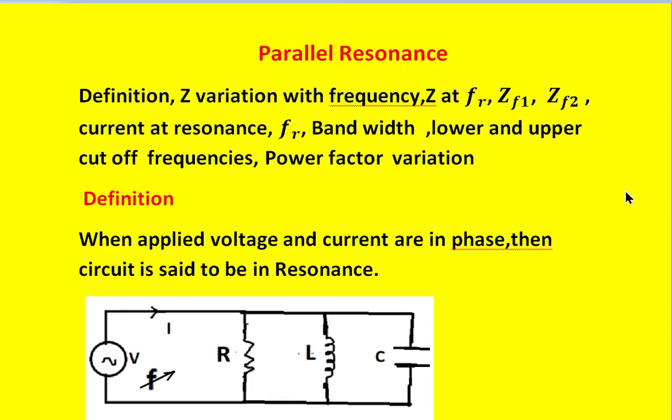It is also observed how the impedance varies with respect to the frequency, and it is maximum at the resonance frequency. Resonance occurs at maximum impedance, that is, the current flowing at resonance is minimum, whereas the voltage across the circuit is maximum at the resonance frequency,